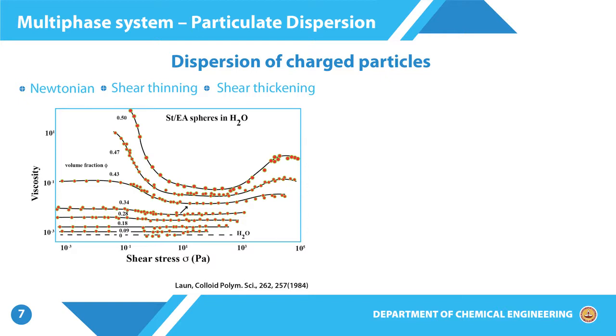So, viscosity is high at very low stresses, and then viscosity decreases and then again it becomes constant. So, this is similar behavior that we had seen in case of polymeric solutions, where we had an initial Newtonian plateau, then a decrease and then again a constant. In that case of course, what we had was several orders of magnitude change in viscosity.